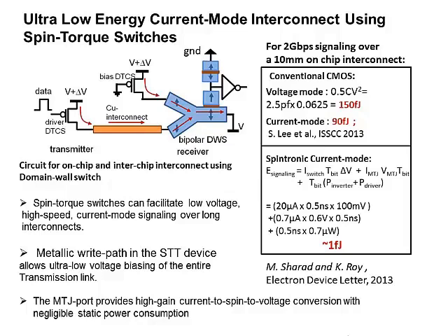The magnetic tunnel junction acts as a resistive device and its resistance depends upon the relative polarity of the two layers, so a magnetic tunnel junction formed at the top of the free layer compares the spin state and converts it into a digital data. If we compare the power consumption of the proposed spin torque sensor with conventional current mode data buses, we can once again get close to 2 orders of magnitude reduction in power consumption.